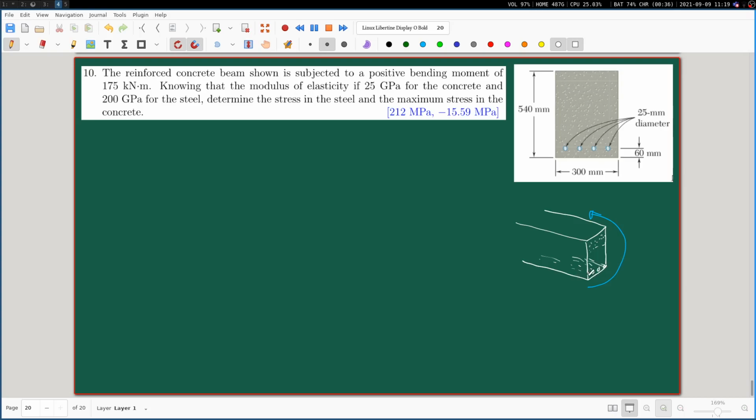Now, as I just said, concrete is not at all good in tension. If you pull on concrete, it has a tendency of just breaking apart. It will sustain a little bit, but it's not very good. However, steel is extremely good in tension. So the practical thing which engineers do in solving for the stresses in these kinds of cross sections is that in that portion of the cross section where you have the tension, they completely neglect the contribution from the concrete.